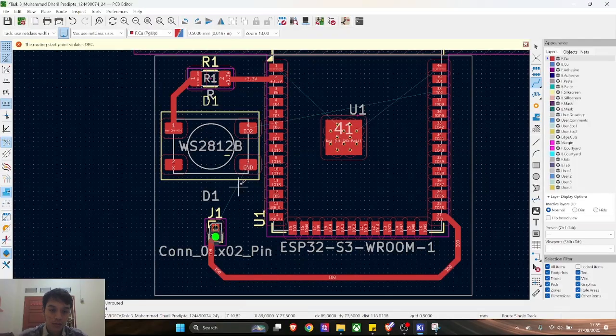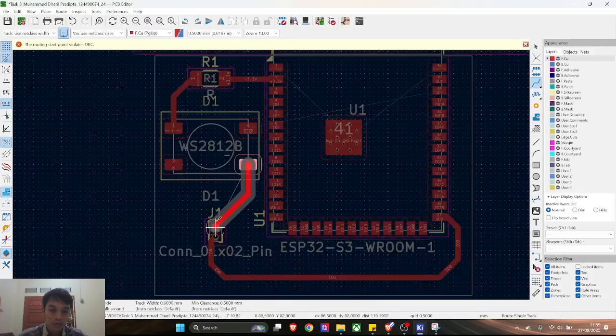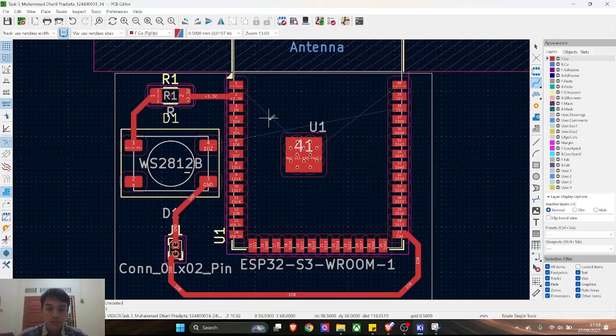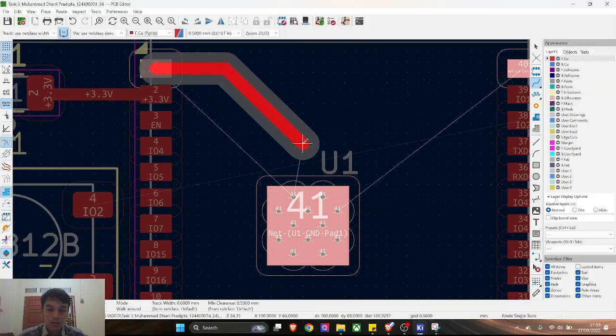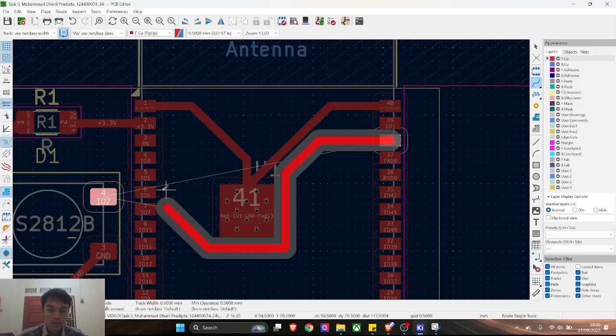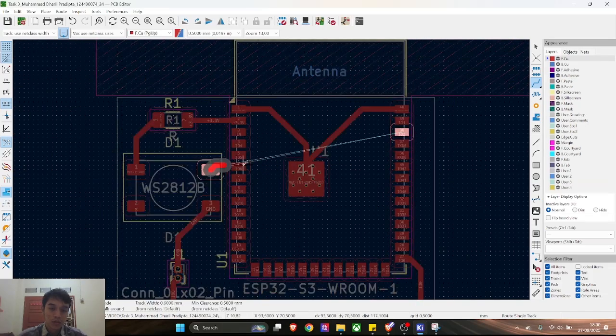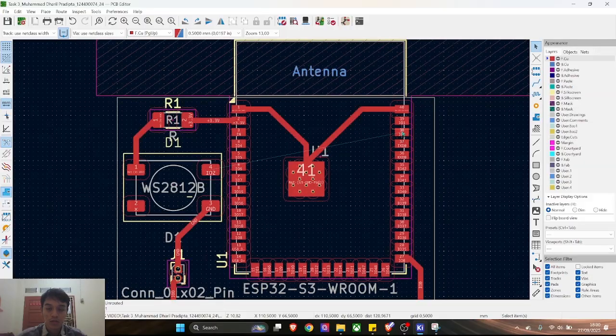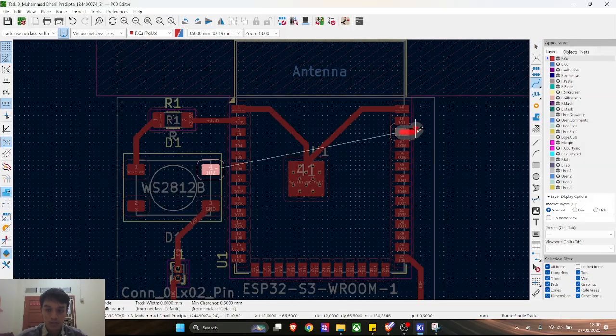Later connect here. I shall connect the ground here. Also here as well. Okay. So since the lines won't interfere with one another, I should select here, X, by clicking V for the via.